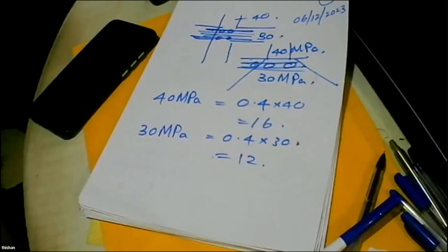But I think the design engineer probably asked for 40 megapascal, which is not a good thing. And anyway, in Sri Lanka, pile rafts are not necessary. Pile rafts cannot work in Sri Lanka because Sri Lanka has bedrock. Pile rafts work only with friction piles, not with end bearing piles. So it's a wrong concept. Any engineer thinking of doing a pile raft in Sri Lanka has to be very careful.